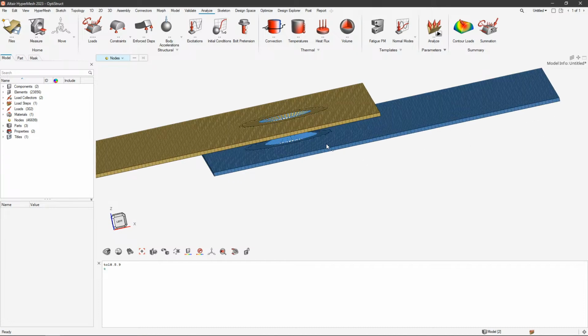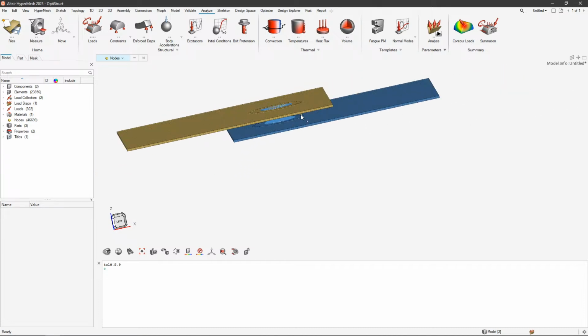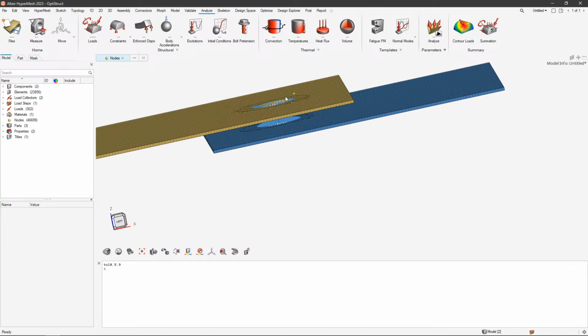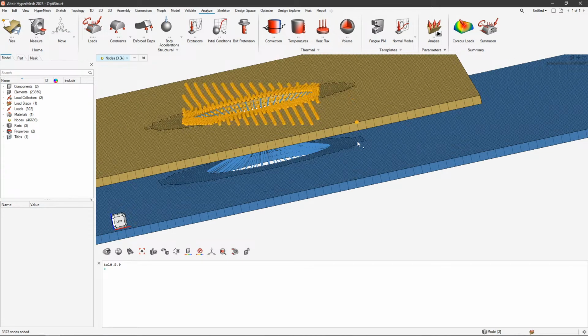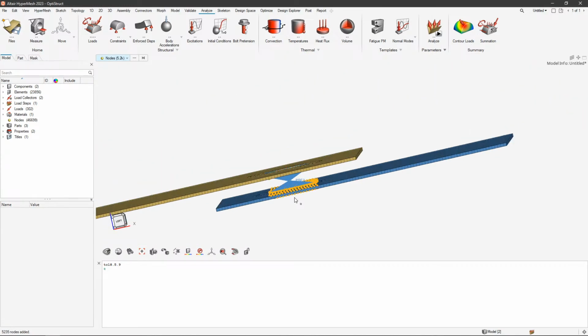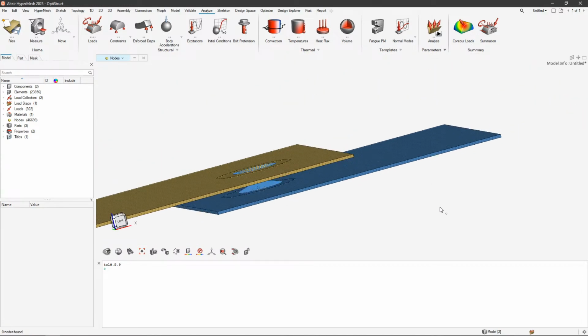So you have yellow, blue, and green. And if you do for each yellow, blue, green, you do intersection of the slave nodes of this RBE with the part. So intersection slave nodes with yellow give you exactly those nodes here, right? Intersection with blue, exactly those nodes, and intersection with green, none, 0. And this is how we find out the grouping. And this is more or less the current implementation, how it's done there. And this makes this model work too. That's pretty nice, I think.